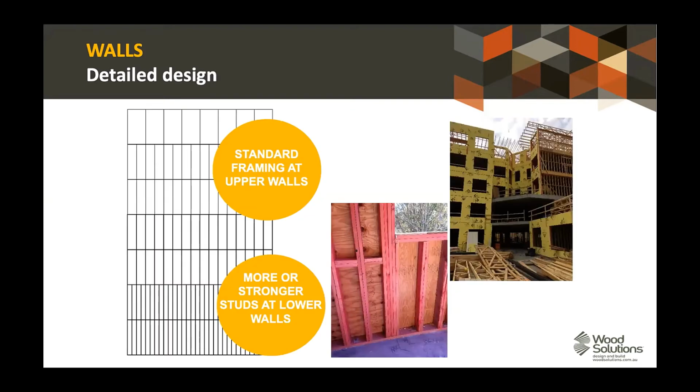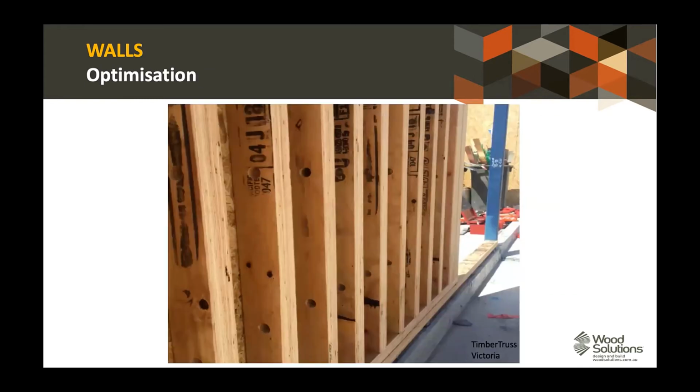So stud optimization, what's the approach? Well, there are lots of different approaches to stud optimization. And again, this is critical with that early supplier involvement to really understand what is the most efficient way of optimizing the studs for a particular builder or fabricator that you're working with. It may be that stud centers remain the same throughout the building. By aligning stud centers, we're avoiding transfers at intermediate stud heights through wall plates, so we're minimizing the bending on the wall plates. Or it may be that actually the most efficient thing is to increase stud centers.